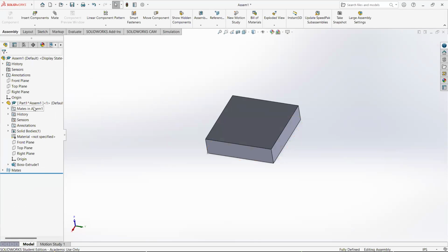So I got rid of the fixed and went back to sort of the old style or the previous recommendation of mating those origins just to make sure things are locked down at 0, 0. Good practice to get into again. In this case, because we built this part in the assembly, it's not strictly necessary like it is in a quote normal assembly.